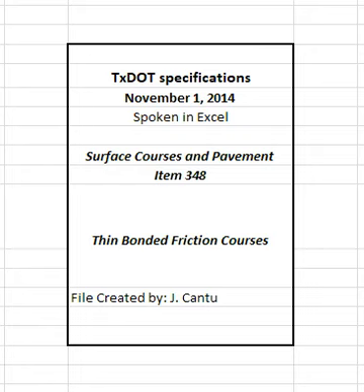2.7.2 RAS. Use of post-manufactured RAS or post-consumer RAS, tear-offs, is permitted unless otherwise shown on the plans. RAS is defined as processed asphalt shingle material from manufacturing of asphalt roofing shingles or from re-roofing residential structures. Post-manufactured RAS is processed manufacturer's shingle scrap byproduct. Post-consumer RAS is processed shingle scrap removed from residential structures.